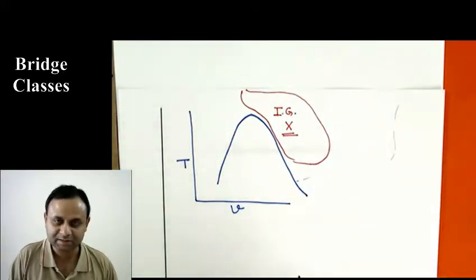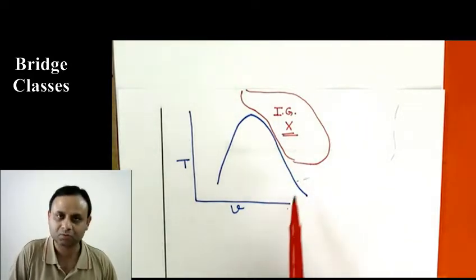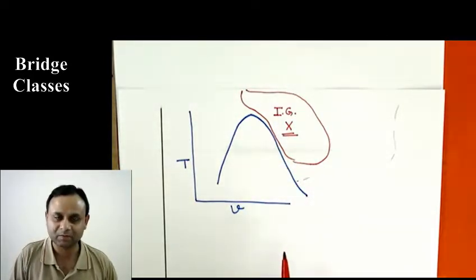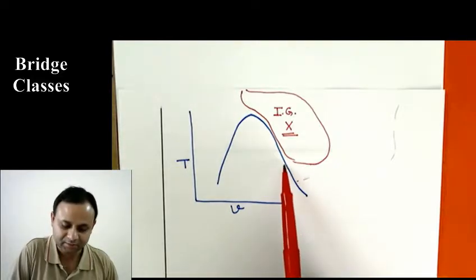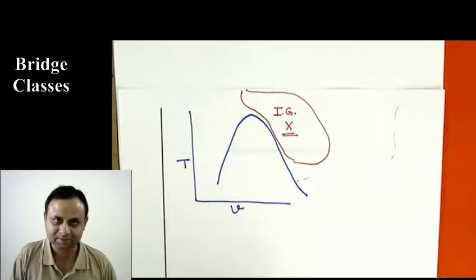And when we are dealing with a steam turbine or cycles where water is the working fluid, the situation is going to be in this region, so don't use the ideal gas law. And when we are dealing with refrigerants, refrigerant vapors are also going to be in this region, so we are not going to use the ideal gas law. Okay.